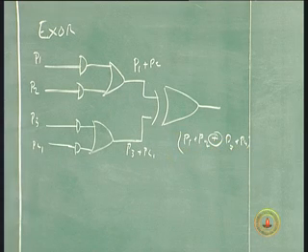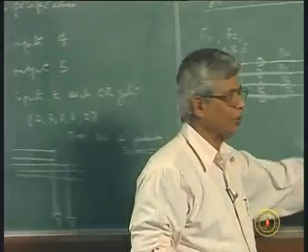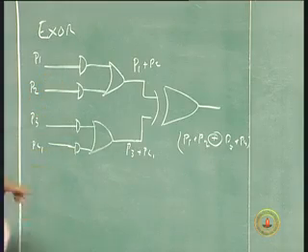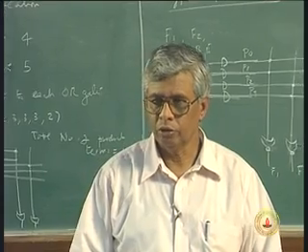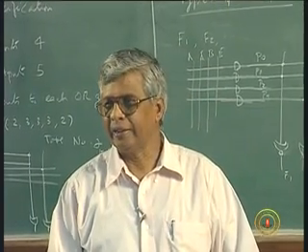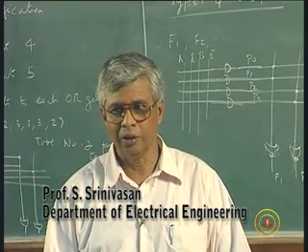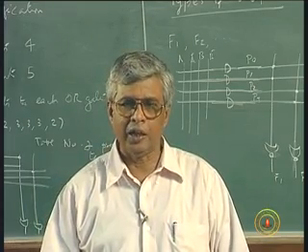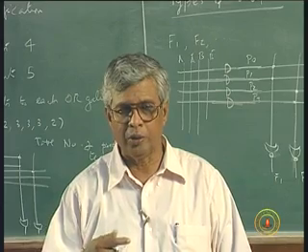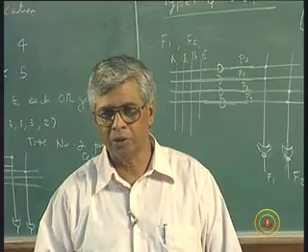So, if you want to synthesize a function in this form, it can be also single. I can also put P1, P2 and exclusive OR them. That is what I would like to have in an adder. Suppose you want to implement a full adder using this, or a parity checker, parity generator, code generator. Remember we did some of those things earlier, but it is not necessary that only one of those terms should be as in to the XOR. XOR will have 2 inputs, but each of those inputs need not be a single AND product. It can be an OR combination of several AND terms, both are possible.